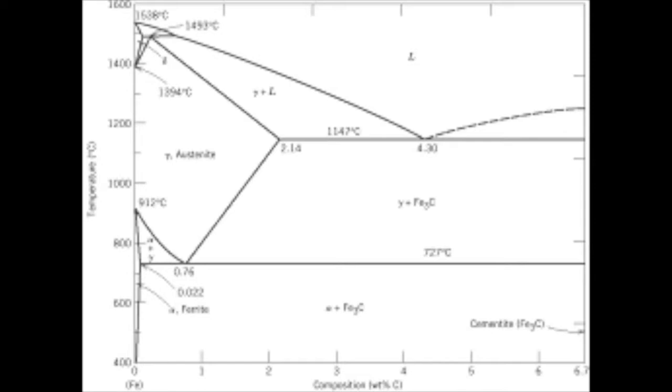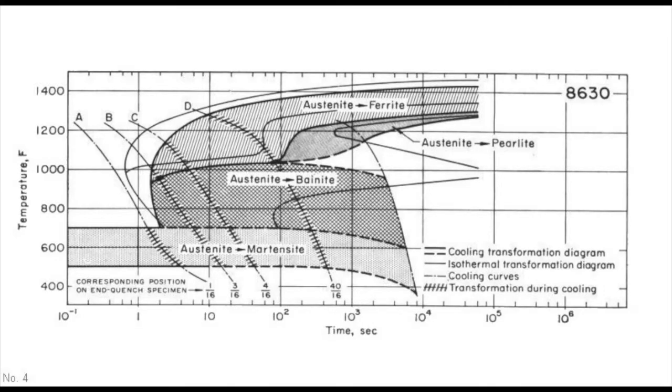which is case hardening. Case hardening is diffusing alloying elements into the surface of a material such that the surface is harder than the rest of the body, consequently forming a case. In order to case harden the shackle, it would be placed in a high carbon environment, either with liquid or gaseous carbon surrounding the shackle. The shackle would then be heated to 850 degrees Celsius for 1 hour to transform the shackle to full austenite.